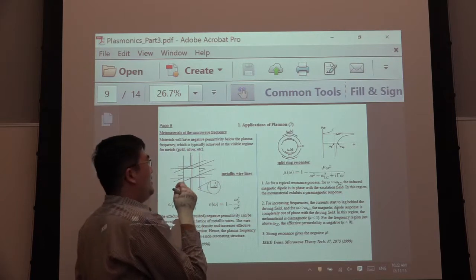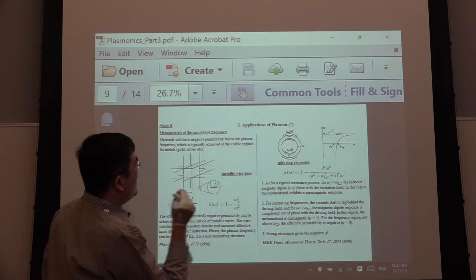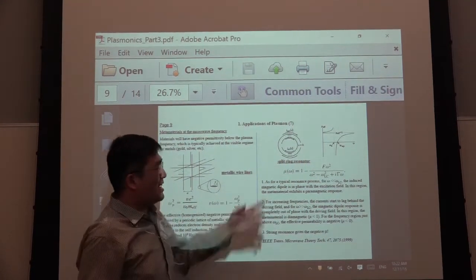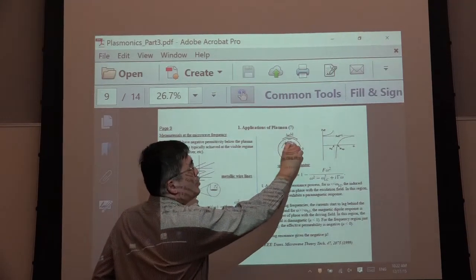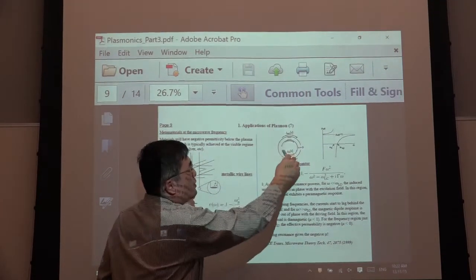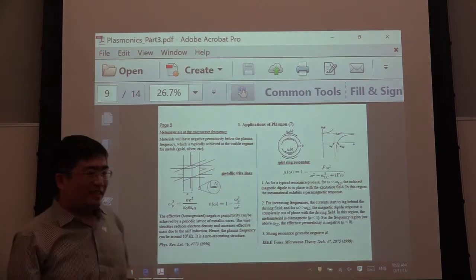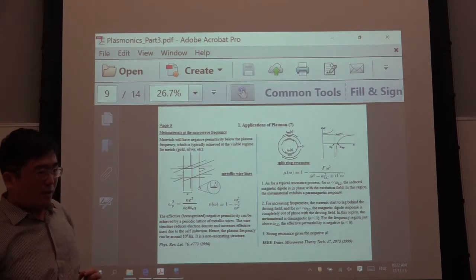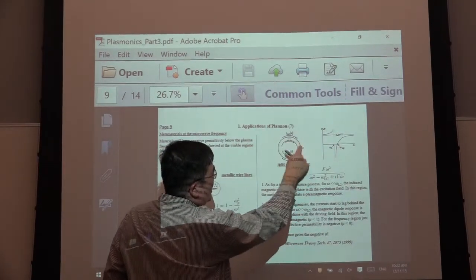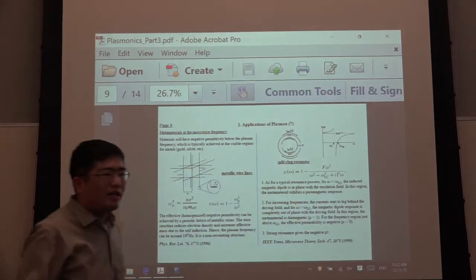Why do they have to do that? It has quite a difference. If you make it closed, it can be a resonator, yes. But it's not good, because for this resonator, the LC circuit depends on the C between this loop, and the L is here and here. If you close it, it's not good and very complicated. So you have to have the opening to get the resonance. L is the circle plus this part. The C part is between the common area here. This is an LC circuit, something like that.